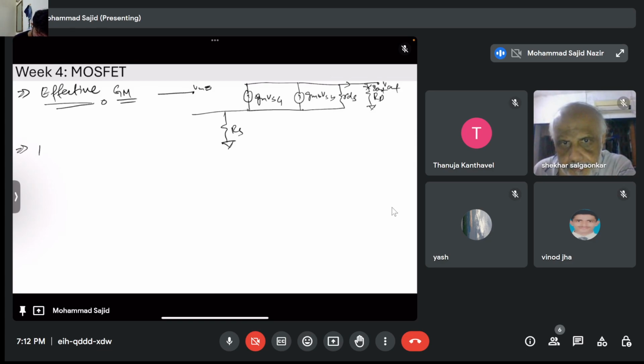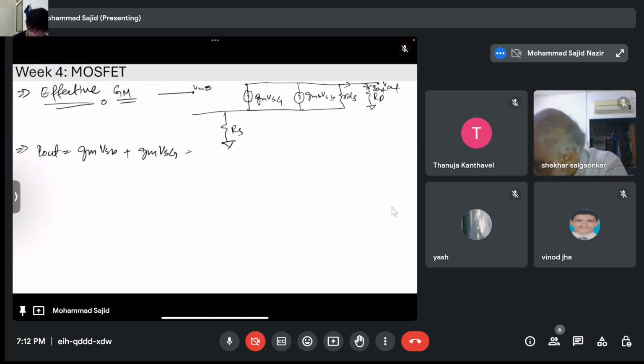So can I write I out is equivalent to Gm Vsb plus Gm Vsg plus, what will be the next one?